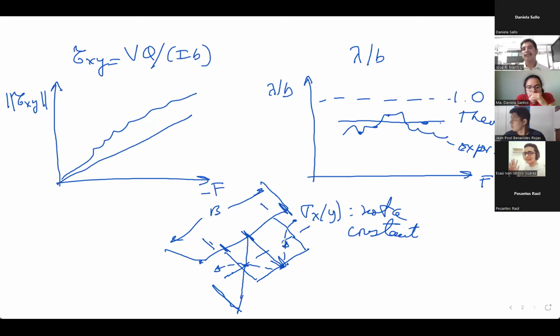For me, it is very important that you complete this chapter with the idea that when you have shear and you have a flange, there is going to be not uniform normal stress distribution, but there's going to be a variation. And this maximum value is important for us as designers. As designers, we need to be worried about the maximum value that we're going to develop.